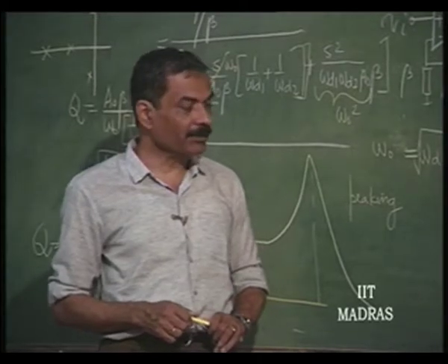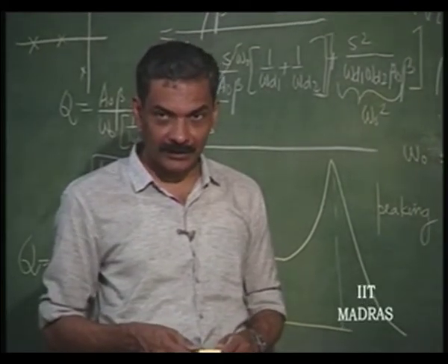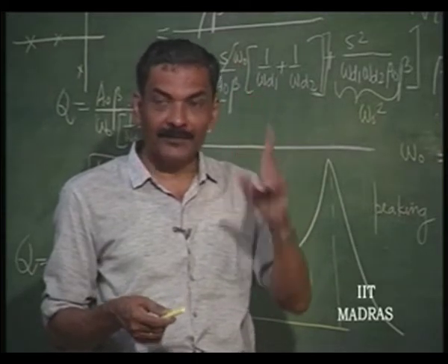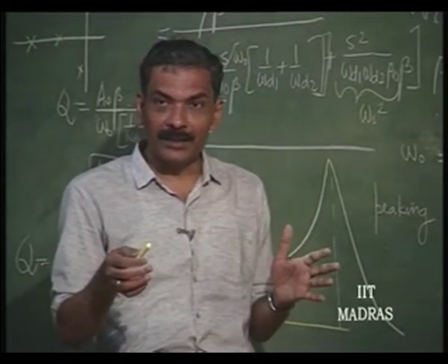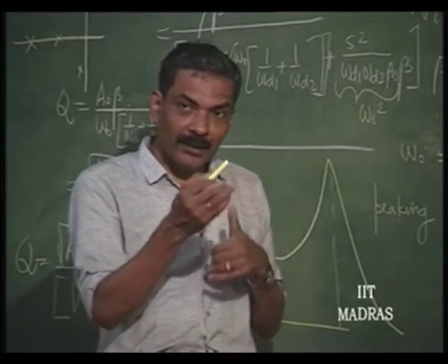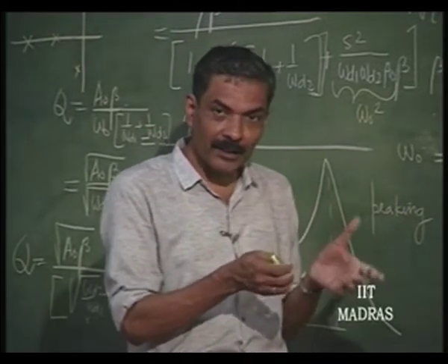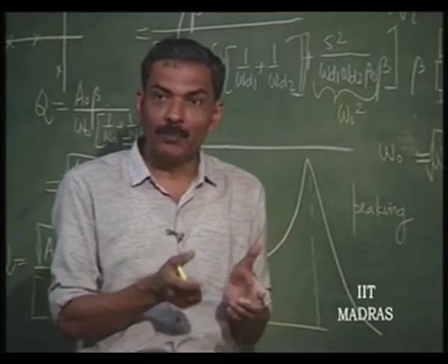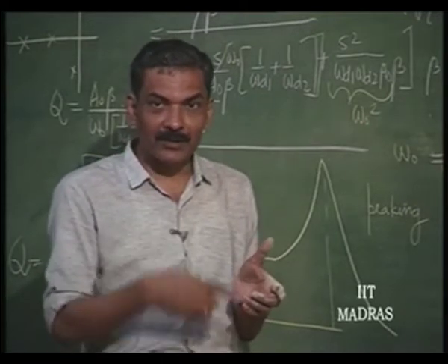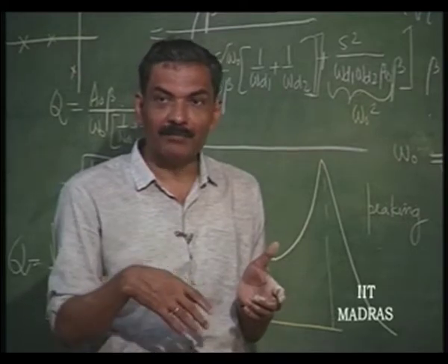That is primarily coming about because of the frequency dependence of the amplifier. Another way of interpreting this is the loop gain becomes equal to 1 in magnitude when the phase shift of the loop gain becomes equal to 180 degrees. What is positive, negative feedback? The output is developed in a manner that input voltage and the feedback voltage are opposing one another. Now, because of frequency dependence, if the loop gain has an additional phase shift of 180 degrees, what is considered negative feedback becomes positive feedback.